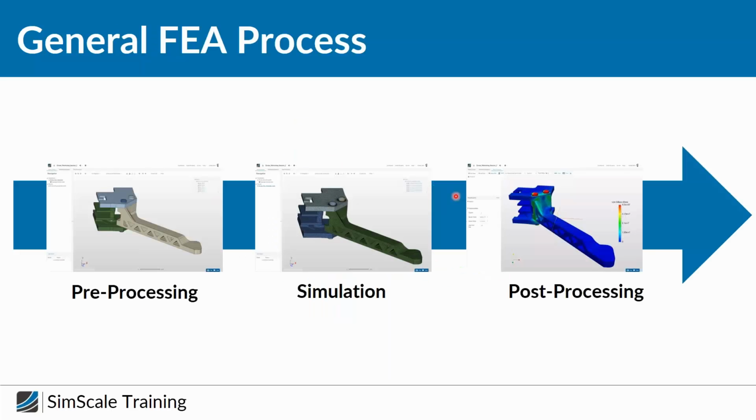Okay, and what is the general FEA process? First of all, we need a CAD model. We have prepared again a CAD model, and we will provide you later on with access to this Onshape CAD model, which you can modify yourself. First of all, we have to import the model, make sure it's clean, and mesh it. Mesh means we have to divide this complex shape into small elements, and we have to be smart and do a strategic element allocation to make sure we only spend elements where we need them, since the fineness of the mesh is related to the local accuracy of the simulation.